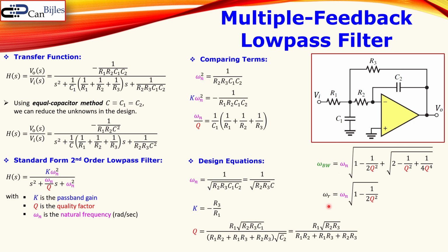This is of course some work, but this is what we can use. Which you also see is interesting because most people, or also in the literature, some books also, say that the resonance frequency is equal to the natural frequency, which is of course not true, because you see here the quality factor also comes into play, so we will have some other definition. There is also the MR here, which is the gain peaking value, which is also related to that Q, our quality factor.